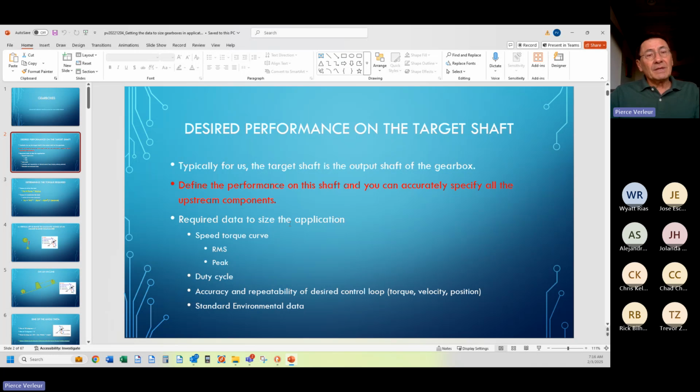Typically, repeatability is the important thing in most applications, because you can then adjust. In the case of the gun target, you just move the target to the right 4 or 5 inches, whatever the inaccuracy was, and now your grouped bullets are in the center of the target. Or what we usually do in shooting is we adjust the scope itself with the dials on the scope. So good repeatability means the machine is performing in a repeatable way, and then we can make adjustments to improve the accuracy to the degree that we need it to be.